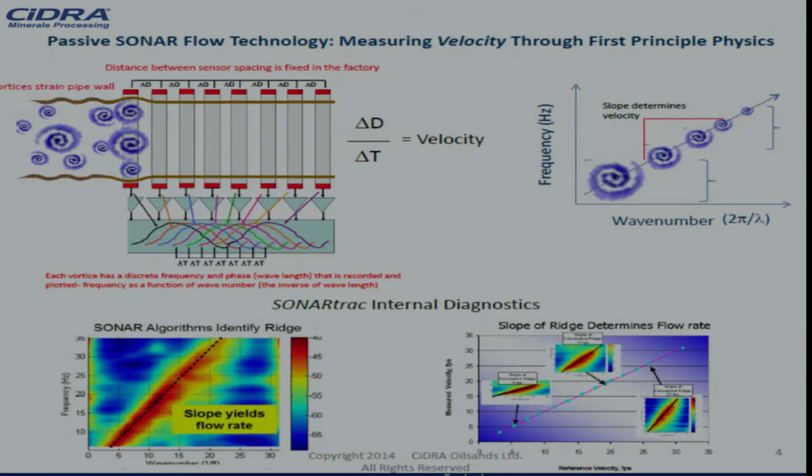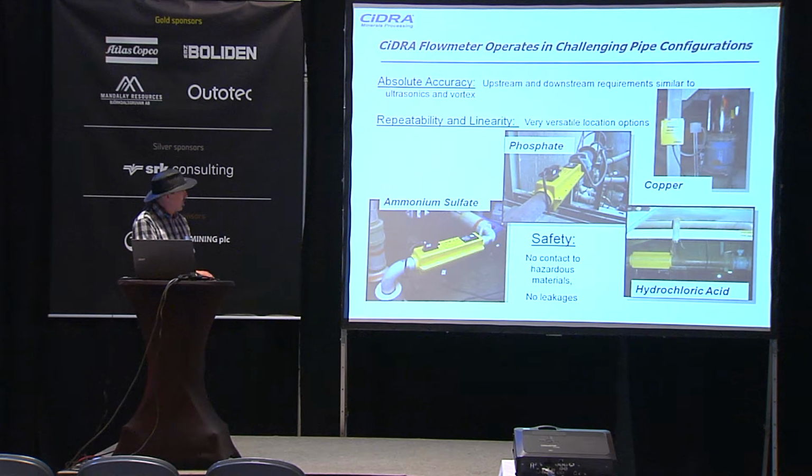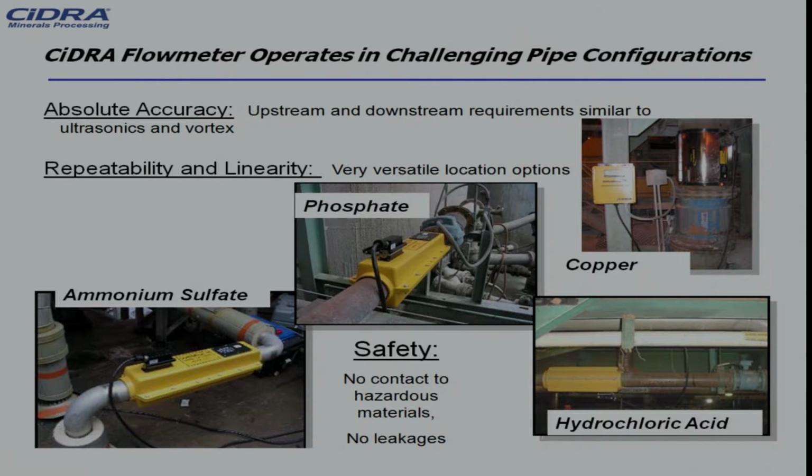And if this is nonlinear, we can simply, by selecting the frequencies, modify and optimize the measurement according to the real flow model inside the pipe. So we get good measurement results even in positions where the straight distances in the piping sections are not available.